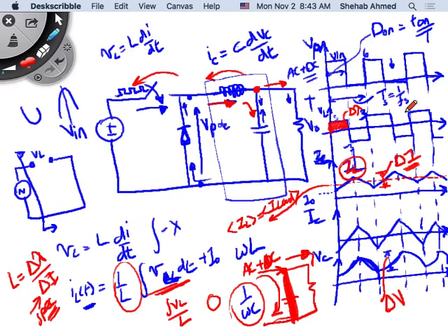It's the amount of flux linkage surrounding the inductor when you've placed a positive voltage across these terminals. That's this area here, right? And this delta I is a spec. It's a specification from the load. Your load requires a nice smooth current with very low ripple, for some reason, because it's a very precise sensor, or because it's running imaging, whatever. Certain loads require very high precision voltage and current with very low ripple, and certain loads don't really care. So I have my delta I, I have my delta lambda, and I can calculate my inductance from there.